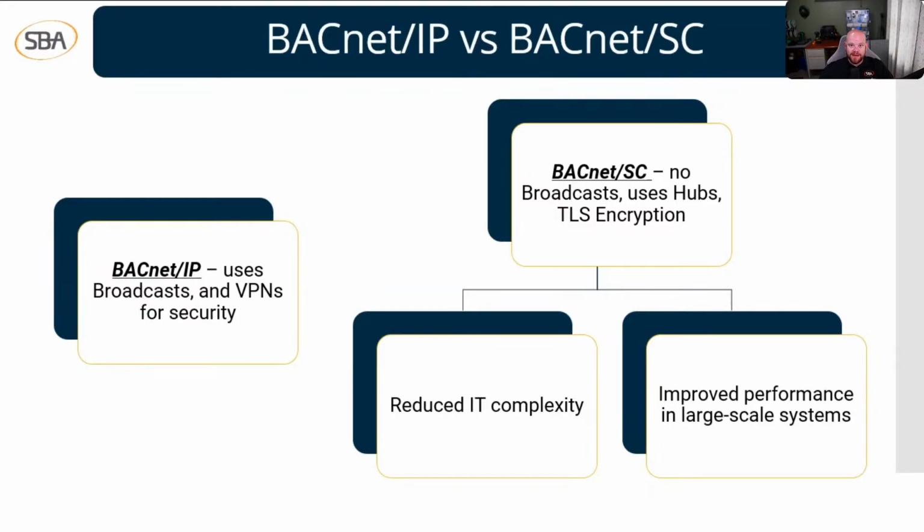So a couple things with BACnet SC is that it reduces IT complexity. This is part of what I was saying with using the VPN on BACnet over IP. It's just a little bit more work for the IT department and us, and so losing that is just one less step we have to worry about. And then on the other side, BACnet SC helps us improve performance in our large-scale systems. So huge buildings, big commercial sites, it just makes things communicate a little bit quicker, faster. Things are more secure. It's just an overall great thing.